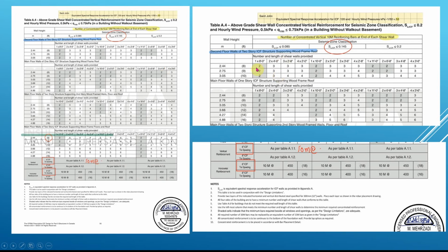And ideally with shear walls, you want to start off with the biggest piece. Again, going back to Lego, you want to use the biggest piece of Lego you can find to fill that in there. If that doesn't fit, then you're going to have to go with two 4-foot pieces. And each wall of the four walls of that house doesn't have to be identical. Each wall doesn't have to have the same.